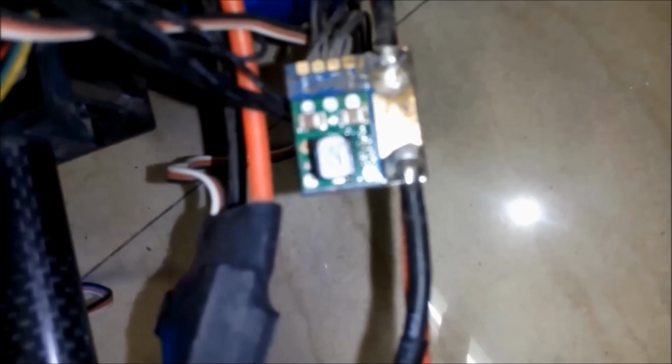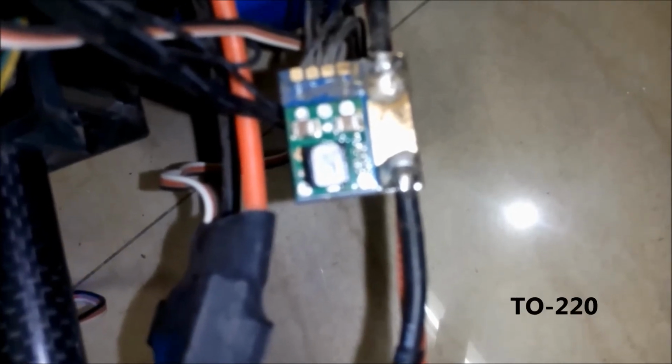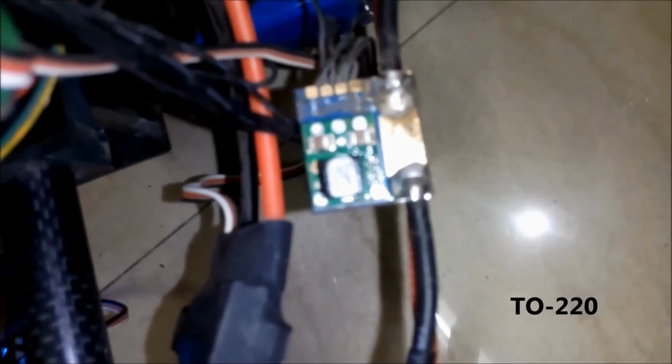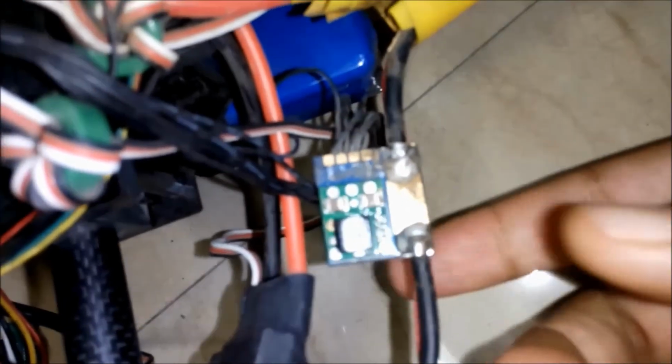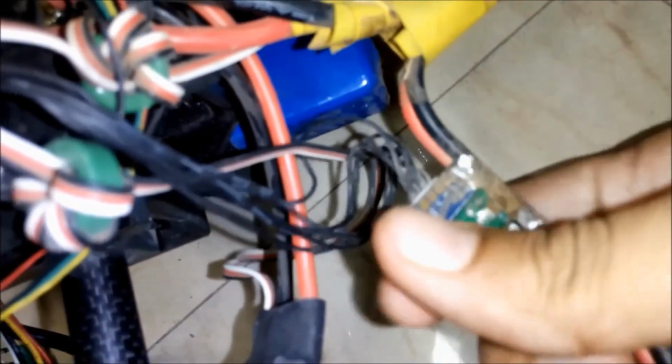For power supply we have used PTH08080, which is a highly integrated low cost switching regulator module, and it can deliver current up to 2.25 amperes. The main advantage of using it in our project was its high efficiency, which is about 95%, greater than a TO220 linear regulator IC. On the other side of this module we have INA169, which monitors the current in real time.